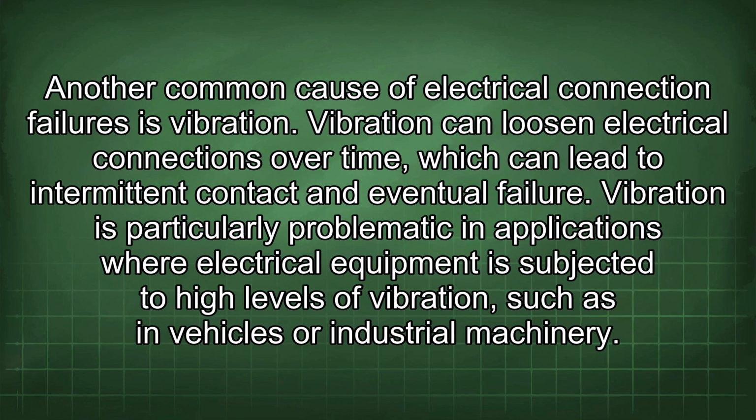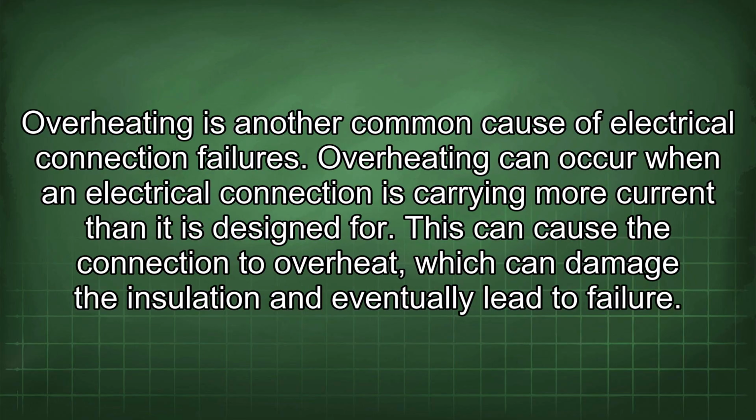Another common cause of electrical connection failures is vibration. Vibration can loosen electrical connections over time, which can lead to intermittent contact and eventual failure. Vibration is particularly problematic in applications where electrical equipment is subjected to high levels of vibration, such as in vehicles or industrial machinery.